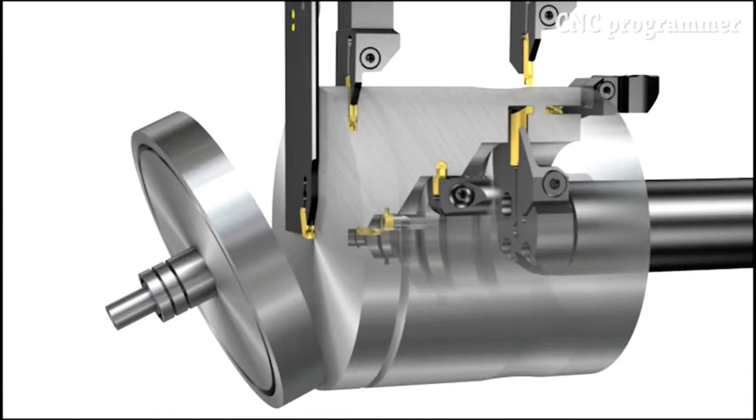But there's different styles of groove tools. The one we've chosen does deep cutoffs and facing. Some of the others are better at turning sideways, like the two you see from the outside diameter on top. And then there are also inside diameter grooving tools that come in different configurations designed to go inside holes. The third type, on the far right, is designed to do grooves in the face of a part so that the groove itself is cylindrical on a flat plane.